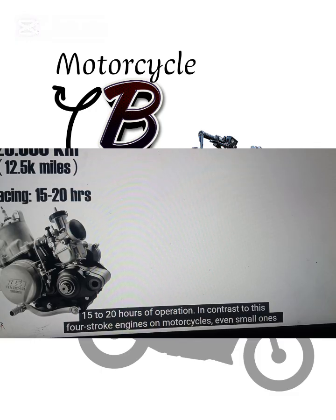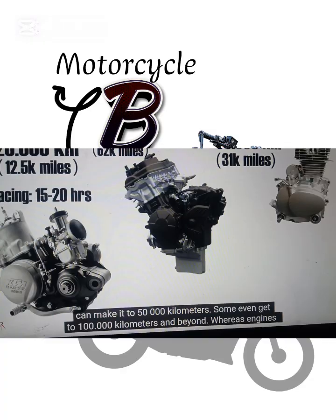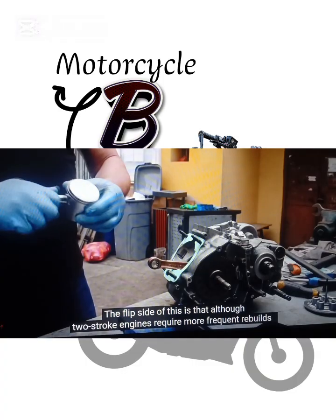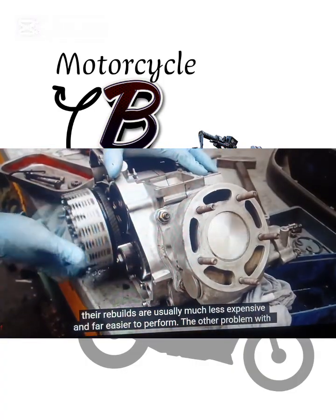In contrast to this, four-stroke engines on motorcycles, even small ones, can make it to 50,000 kilometers. Some even get to 100,000 kilometers and beyond, whereas engines on cars and trucks regularly make it past 300,000 kilometers. Some even get up to 1,000,000. The flip side of this is that although two-stroke engines require more frequent rebuilds, their rebuilds are usually much less expensive and far easier to perform.